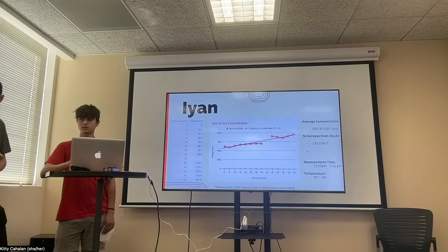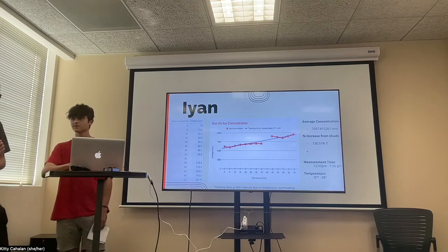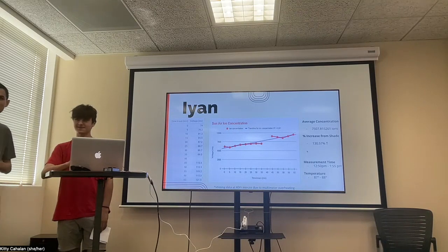I'd say with that, there's a possibility that the sun was just heating up your instruments and causing it to drift, so you have to convince yourself that wasn't happening. I mean, it could be a correct measurement, but it could also be a drift. I don't know. That's definitely possible. I would have to do further analysis to get a better result. Yeah, you could check that by doing it opposite, by having it in the sun and then moving it into the shade, maybe. I'm not sure if that would work, but there'd have to be some way of convincing yourself that it's not just the gadget heating up. Fair enough.